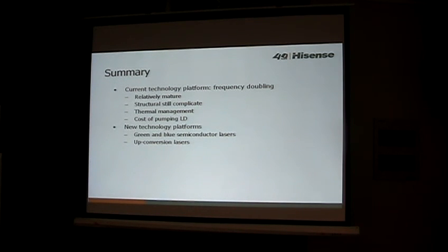So you can see, now we have red semiconductor lasers mature. Almost every 10 years, we can work out one wavelength. We don't know exactly how long it will take for green, but if your time frame is, say, 3 years and you want a product, definitely this is not the technology platform you want to go with. And also another one is the so-called upconversion lasers.